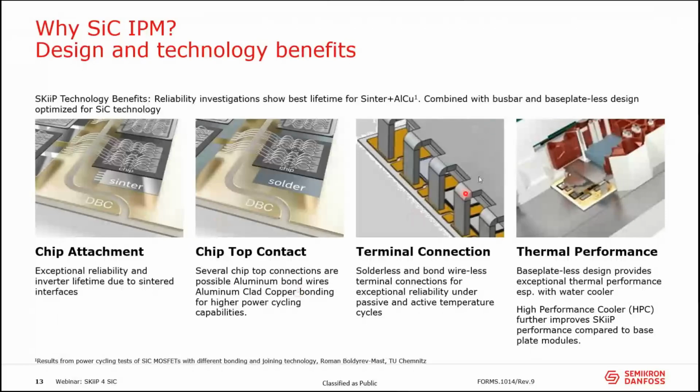We have already seen the terminal connections. That means that each chip has its own bus bar leg, so that the current sharing in the module is optimized. So that's additional reliability for passive and active temperature cycles.